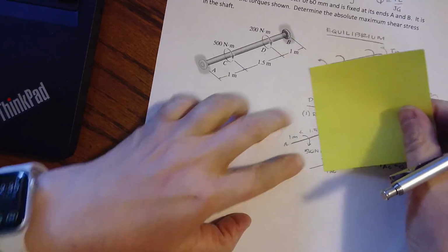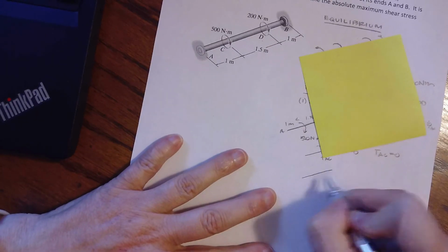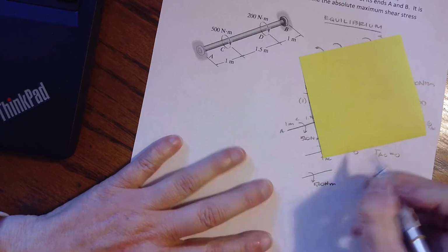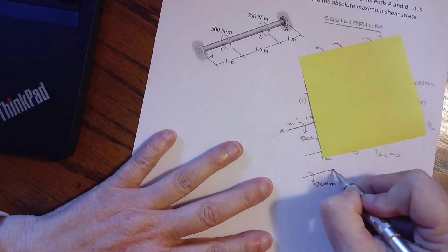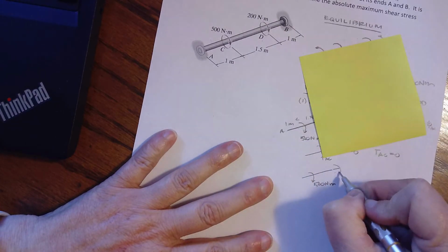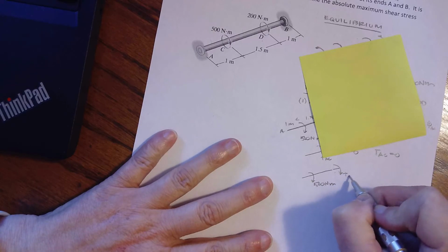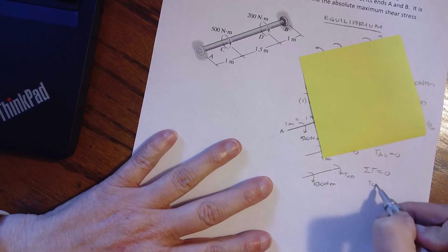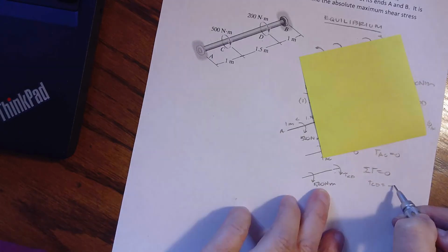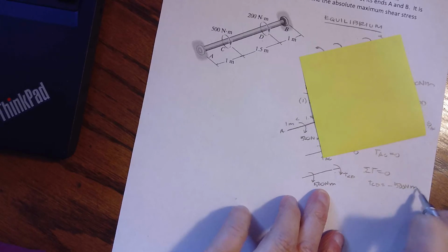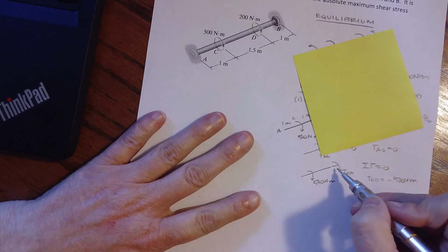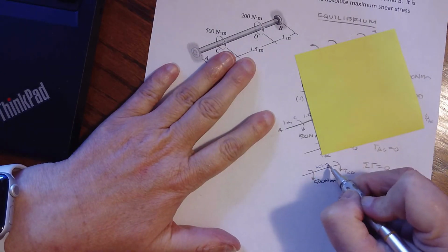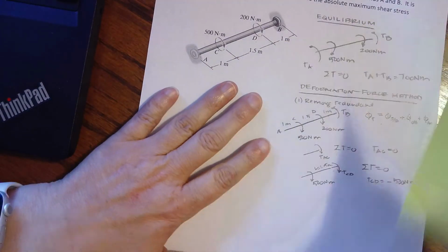Now we're going to move back again. And I have 500 Newton meters. Internally, I'm going to assume positive rotation, torque from C to D, and I'm going to sum those torques equals 0, and I'm going to find that torque from C to D equals negative 500 Newton meters. Perfect. I can now determine the angle of twist in here. The length of this segment is 1.5. That's what I'm cutting, is that length.